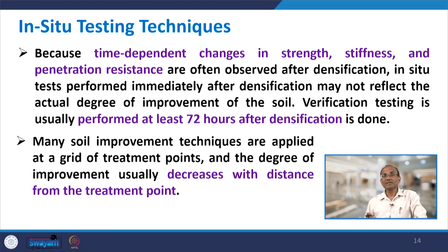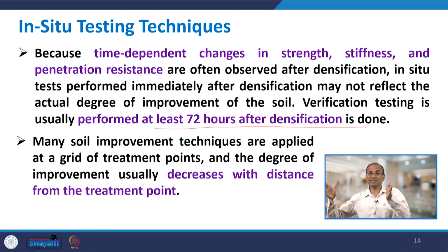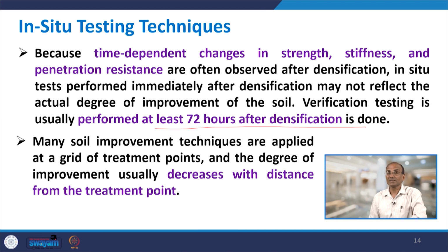So, therefore, in situ tests performed immediately after densification may not reflect the actual degree of improvement of the soil. Verification testing is usually performed at least 72 hours after densification is done, because for the densification to be effective, some minimum time is required. It is suggested to wait at least 72 hours, because as time passes the densification might become effective.